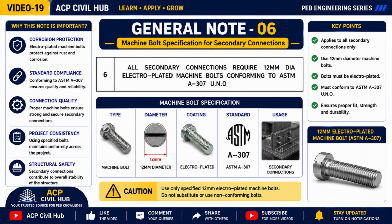Let's continue with general note number 6. This note specifies the machine bolts that must be used for all secondary steel connections in the project. According to the drawing, every secondary connection shall use 12 mm diameter electroplated machine bolts conforming to ASTM A307, unless noted otherwise in the detailed drawings.